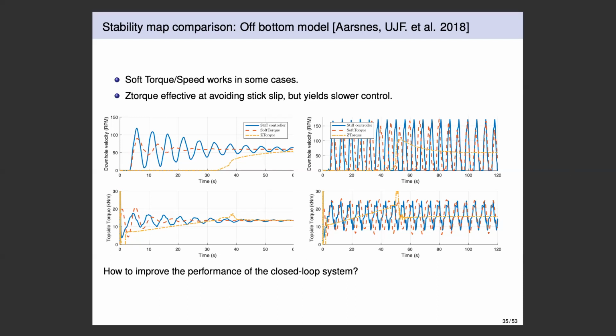And especially if the controller requests a very large acceleration, which will definitely blow up the limit of the top drive controller. Yep, and we've seen the same on power requirements, even though we might not be at the top drive torque limit as far as the top drive machine itself. With the generator set that we're running, if you had, let's say, 2 generators running instead of 3, we've seen stick-slip come from that poorer level of control, if you will.